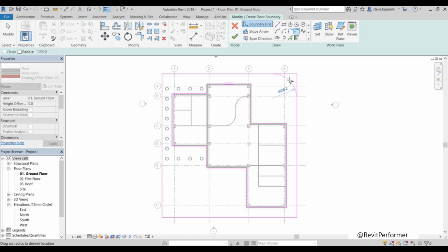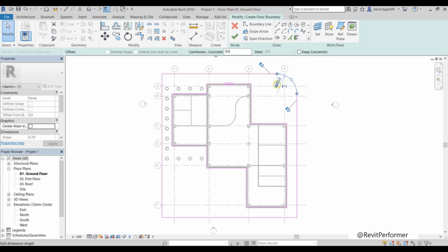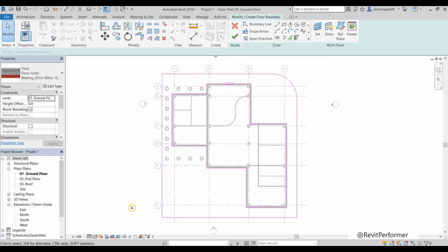You can try and get it to 5,000, or you can simply click to place and afterwards come back, select the curve, and change it to 5,000. We can also select the fillet arc, go to the options bar, turn on the radius, and change it to 5,000. So now when we select the 2 lines, then the bottom left-hand corner, it'll automatically generate that.